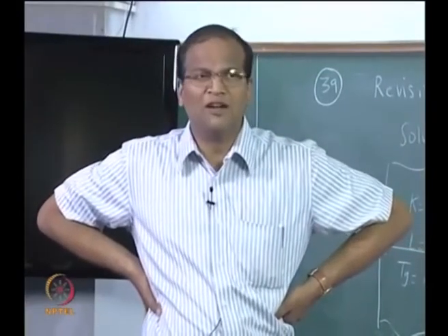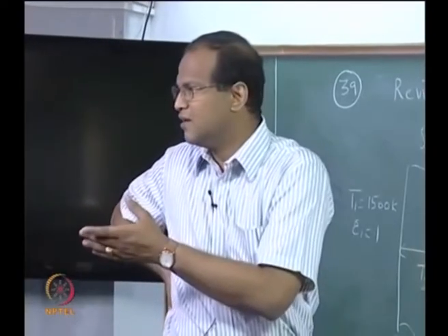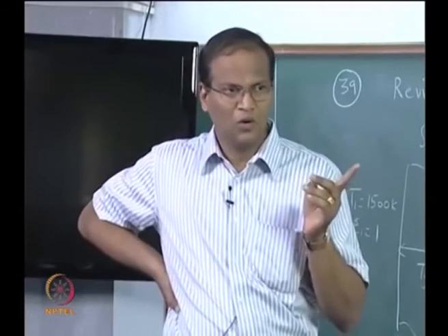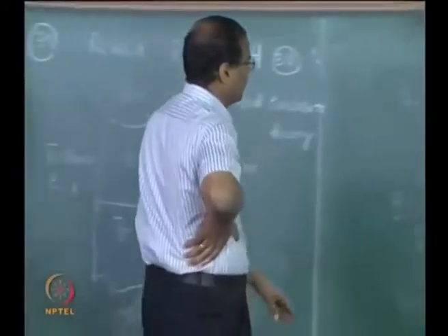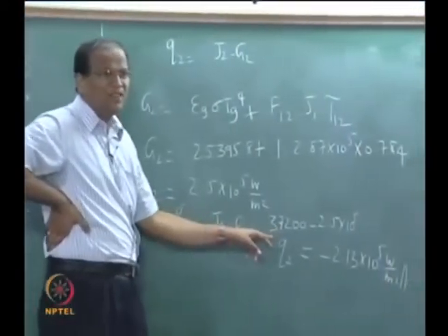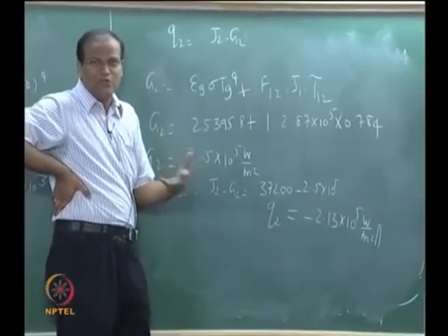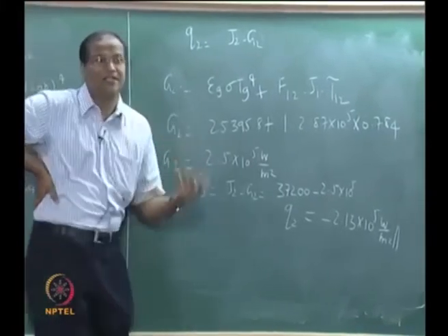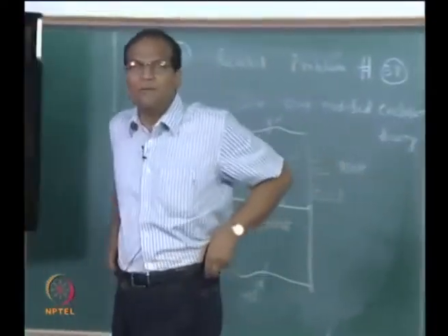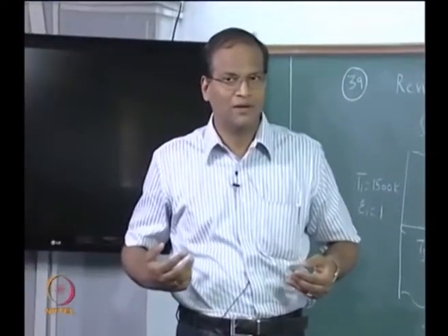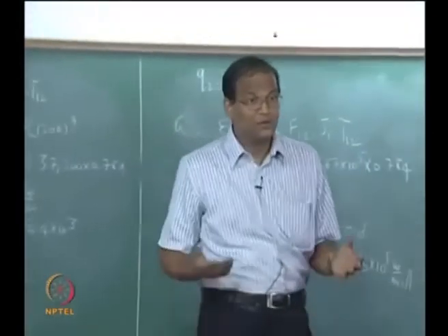So, a solution to your radiative transfer equation does not guarantee equilibrium. So, the gas is getting heated, is it? Is that correct what we got? Okay, because 235 is coming out from the left wall, 232 is coming out from the left wall, but this fellow is able to absorb only 213 kilowatt. So, 19 kilowatts every second, 19 kilojoules per second of energy is being absorbed by the gas. The gas has to get heated up. So, my equilibrium temperature should be above or below 1200? It should be above 1200. Just see whether you are getting it. I hope so. Okay.